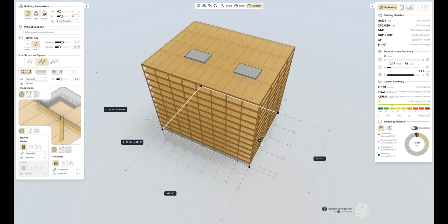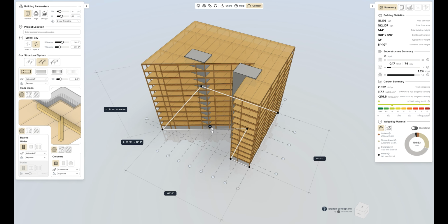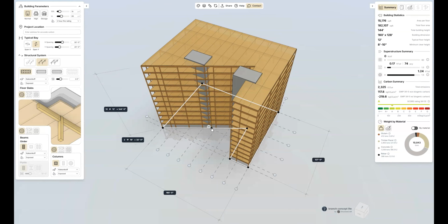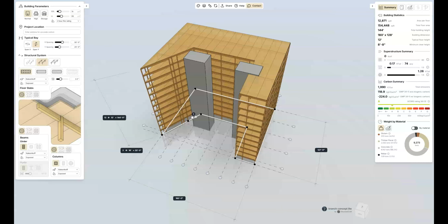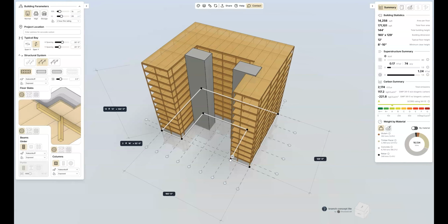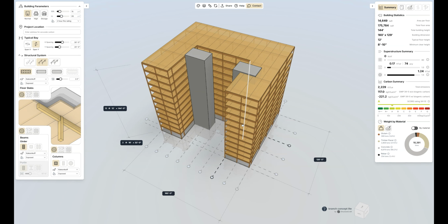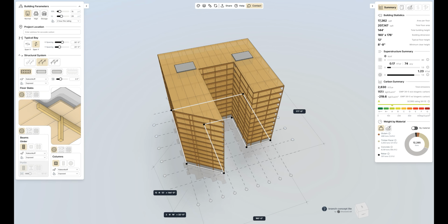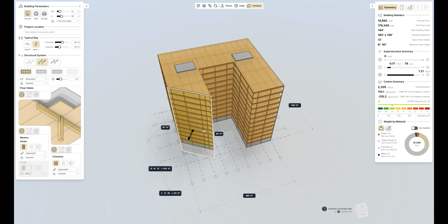Branch allows you to make buildings with many different shapes. In order to do this, you can click on the building outline located close to the ground floor. You'll see a plus icon, and clicking this will add a control point. Once the control point is added, you can click on the edge and drag that to create different shapes. If you want to remove a point, hovering over an existing point will bring up the delete icon, and clicking this will delete the point. Pressing Shift when you push and pull will give you the option to drag a surface orthogonal to your view.